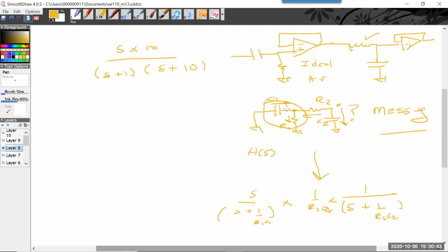Same thing here, the charge and discharge of this capacitor is affected by this. But because this op amp is ideal, the current going into it is 0. So really, from an analysis perspective, you can just get rid of it. And you just have a classic RC circuit that you would have seen in 98 or differential equations, right?